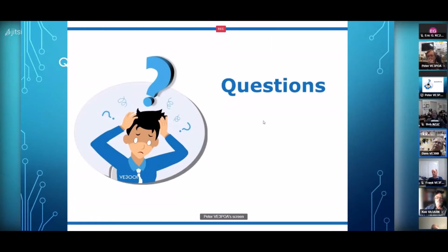Next question is your footprint for that SMA connector. Did you have to make that yourself, or is that standard in your CAD? I found it somewhere when I was using version 5 point whatever of KiCad, and I was using that for the longest time. I had not used version 6 yet, and I decided a few days ago to actually start using it, so I had it all loaded, ready to go.